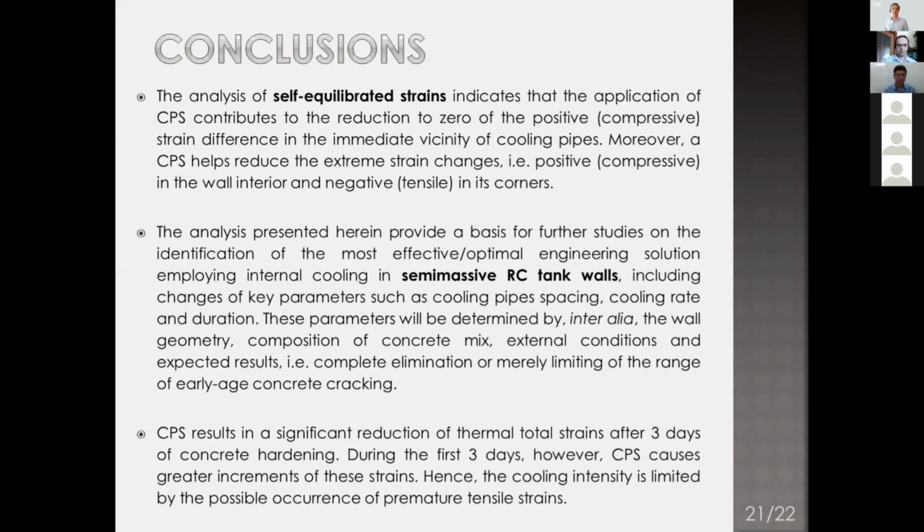And the last conclusion: CPS results in a significant reduction of thermal total strain after 3 days of concrete hardening. But during the first 3 days, CPS causes greater increments of these strains, hence the cooling intensity is limited by the possibility of occurrence of premature tensile strains.